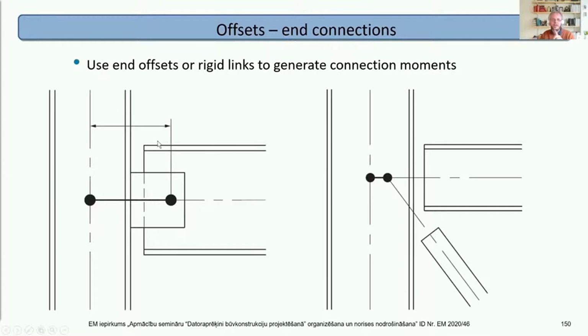But be careful you don't under-design the beam. If the beam span is from here, then there is loading at the end you'll be missing out on. Watch out for that. Do not under-design the beam. Another option is to take the beam to the column face. Program will do this automatically, and that gives sort of a compromise between the two. Now, which one is correct? Should you have just one? Should you have two models? One for the columns, one for the beams, and so on.